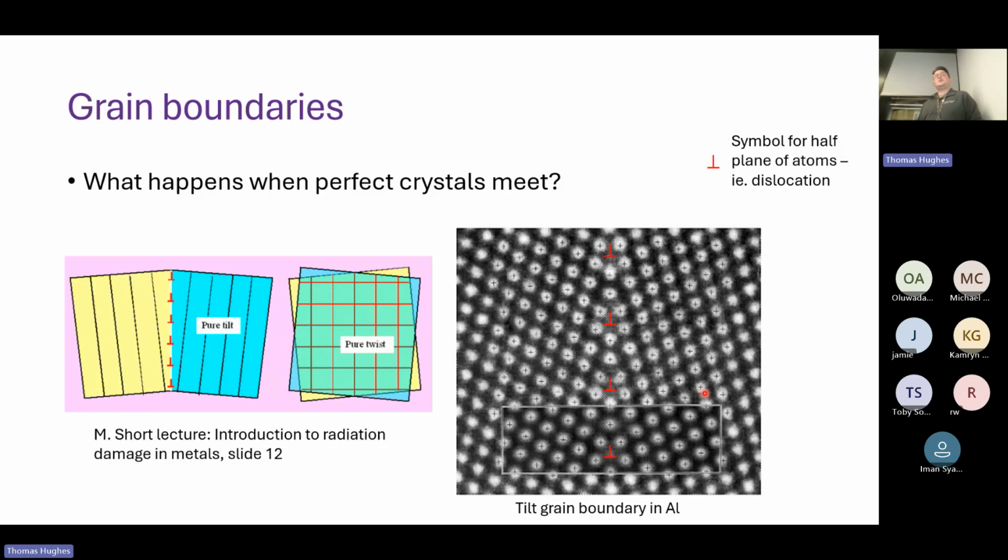So grain boundaries are a place where you have lots of slip. Material failure might also happen, a crack might grow around a grain. But you have a lot of deformation here, and grain boundaries are very important to think about. But they're essentially a big line of dislocations, and they're just two crystals right next to each other.